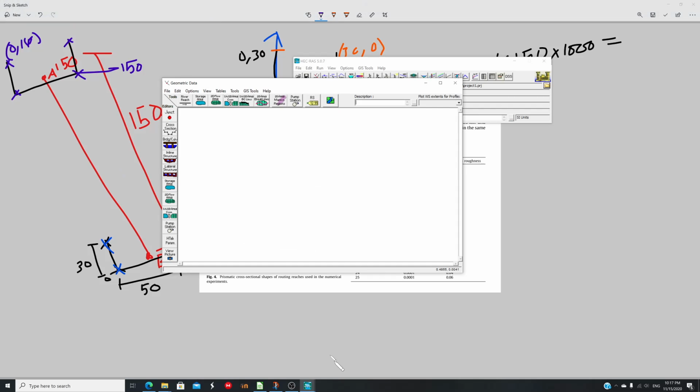To do so, first we need to create a river reach. So I'm creating this as a river reach. Let's name this river as River 1; you can name it anything. This is the reach. One river can be broken down into many reaches, so I just want to name this as River 1 and Reach 1. Now the next thing is to put in the cross section that we have just made here.